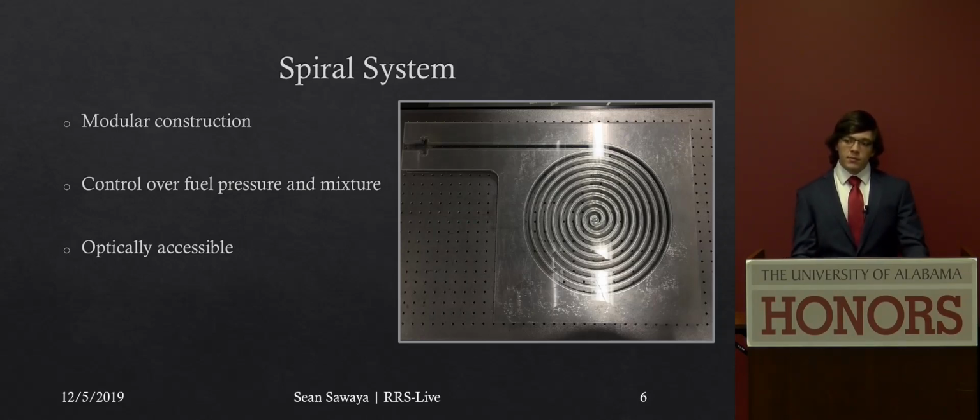What type of reactant gases are you going to be using? So we are using three main gases within our system. We are using methane, which is our fuel, pure oxygen, which is our oxidizer for the fuel, and then nitrogen, which is our inert gas, which will be simulating regular atmospheric air.